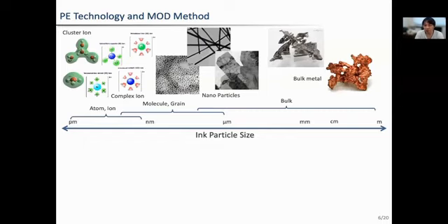However, when you need the properties of nanomaterials, such as big surface area and high speed reaction, you have to choose a smaller particle size in the ink, meaning ion or atomic size level. So I think we have to make ink designs down to the ion or atomic level, rather than the particle size level, for using nanomaterials in the devices.